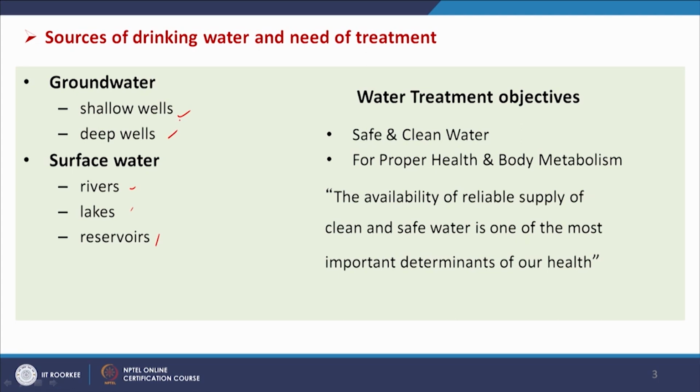If we go deeper, the wells normally become safer and require less treatment, and shallow well water normally contains more contamination like arsenic, fluoride, etc., and requires more treatment.